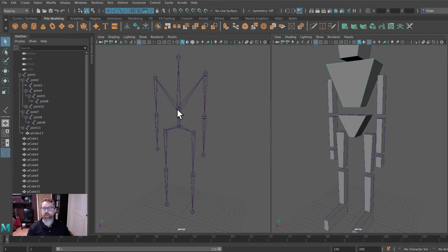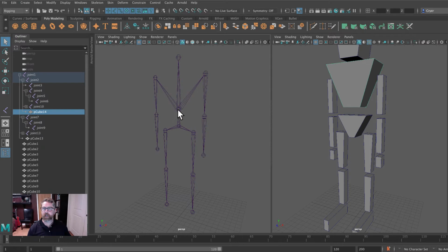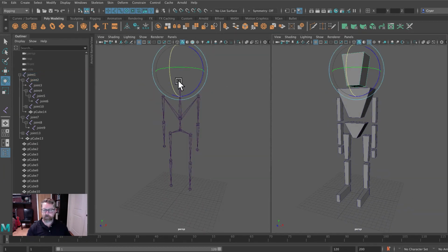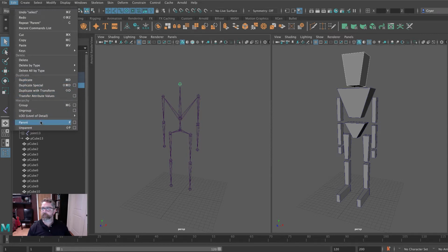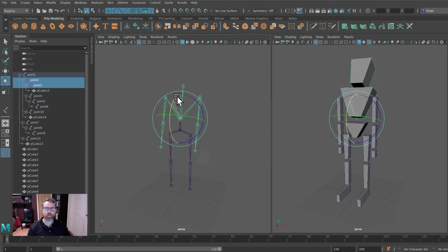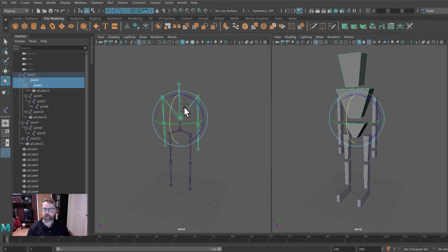And we'll just go through this process. So this piece, shift select this joint, which is our waist, and we'll come to edit parent. You can hit lowercase p on the keyboard. And everything except the root is going to rotate. So we'll rotate from here on out to make sure that that works. We'll grab our head piece, best done with the Q key, and our joint 3 in this case, and we'll come to edit parent. Then if you wanted to check that, you can pick two joints and see how those are working. That's essentially what we're doing in our animation, having them crash into something and then come to a progressive chain reaction stop.